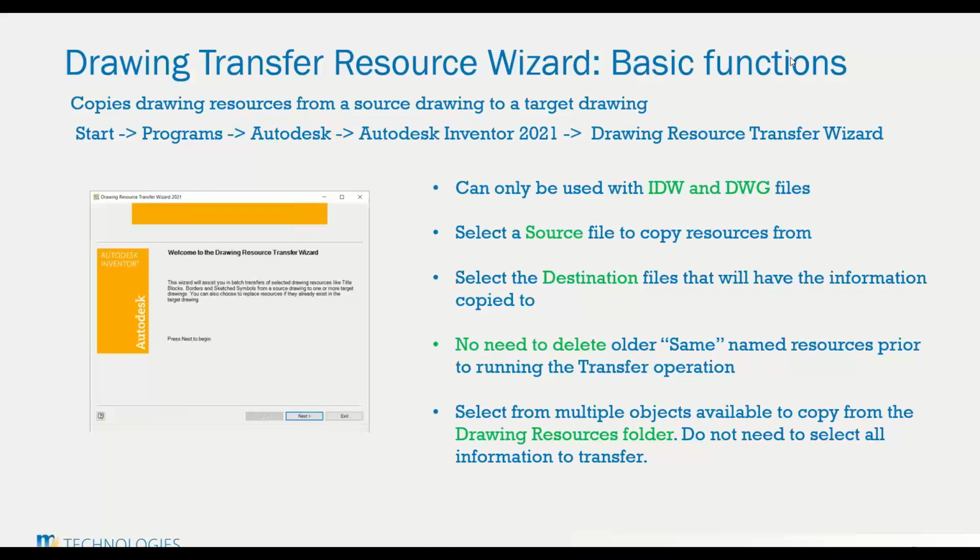And next up, I just wanted to take another few minutes and just talk about another tool that I field some questions on throughout the years. What happens if you have an update in your title block and you have hundreds and hundreds of older IDWs, DWG files that have that older information title block? What is very painful is if you don't understand or realize this tool is available to you, you're deleting title blocks and swapping out and putting in new ones.